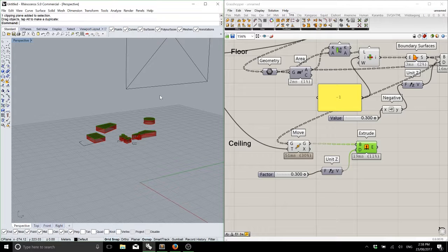If it belonged to the wall layer, we didn't know if it was the outside of a wall or the inside of a wall. It just didn't have the properties assigned to it. It didn't define the material. All that mattered was as long as you hatched it the right color or the right hatch pattern, the builders would know, oh yes, that's made of concrete. What BIM does is it says you can take an object in a CAD program and assign it that material. You can say, this is concrete. Or this is a toilet. Or this is a bedroom. And then whenever you move that room, all the properties that are associated with it move with it.